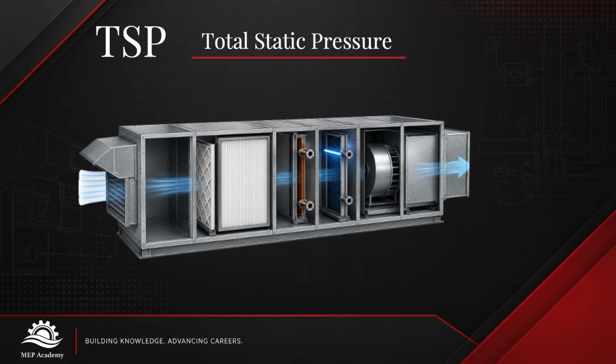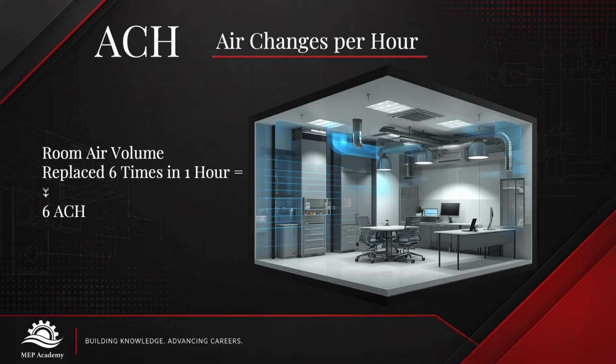Total static pressure represents the overall static pressure difference across the fan and is used when evaluating fan and air system performance. It provides a broader picture of the pressure the fan must produce to move the required airflow. Number 20. ACH, air changes per hour. ACH describes how many times the volume of air within a space is replaced or exchanged during 1 hour.